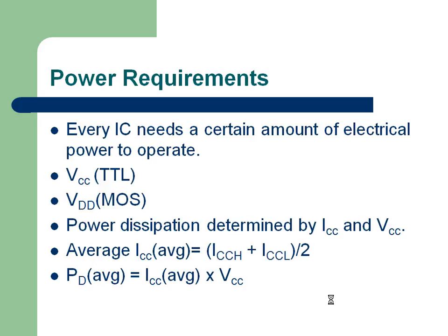So, for average current, we usually do the calculation like this, because there is an amount of current involved from low to high, and there is a current pumping required when the output is low, and something different when the output is high. But in general, we don't know what value a gate is maintained at. So we assume 50% probability for 1 and 50% probability for 0 and take an average of it. That average product we consider as the power. Same thing for CMOS also.